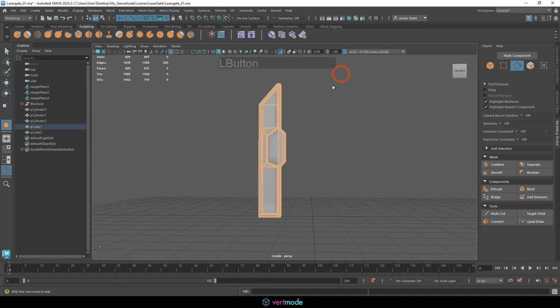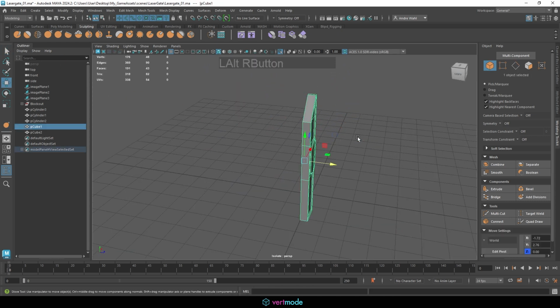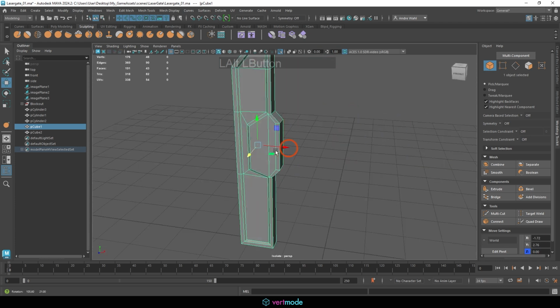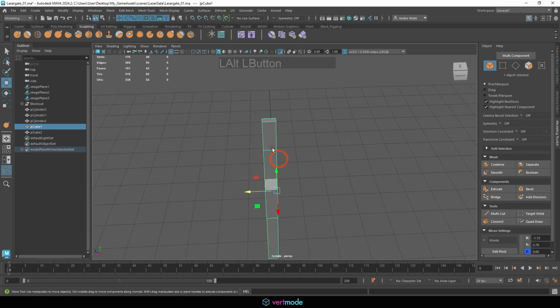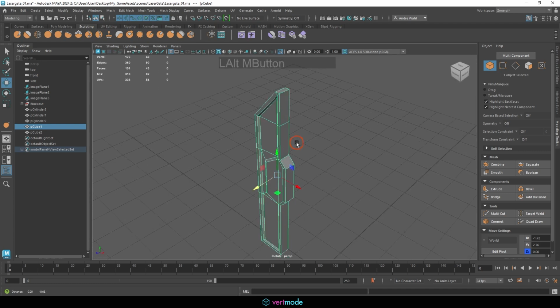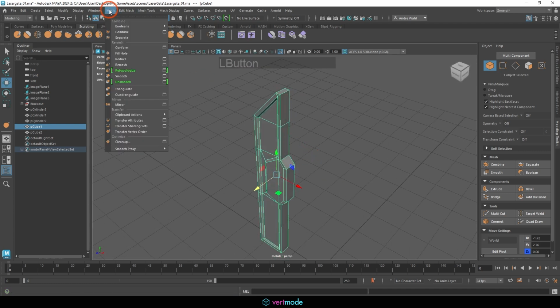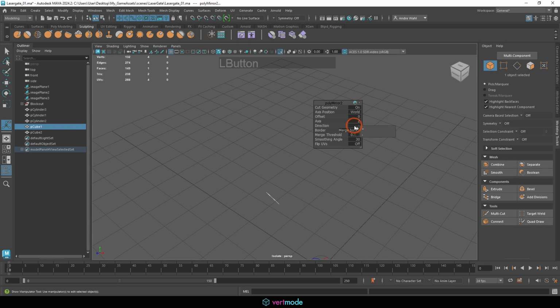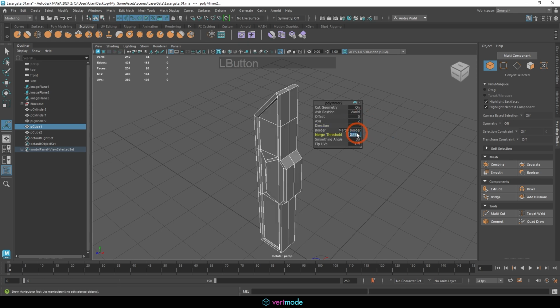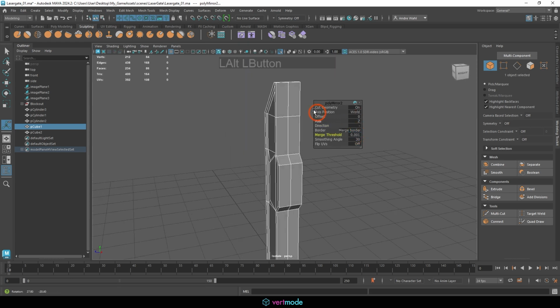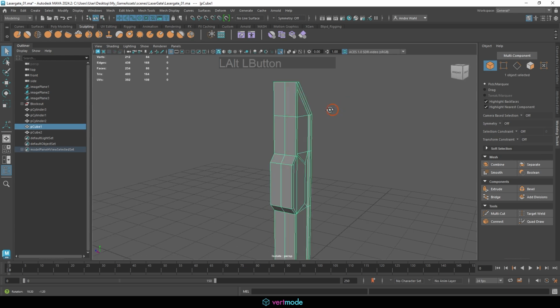So that makes me excited because it makes it a lot easier to do the next step, which would be to mirror this back and basically just use the bevel tool. So since we have this already centered here, should be good to go. We can just come into our mesh. We can use a mirror like we did previously, but this time we're going to do Z minus 0.001, so we're going backwards. And this will give me this front and back.